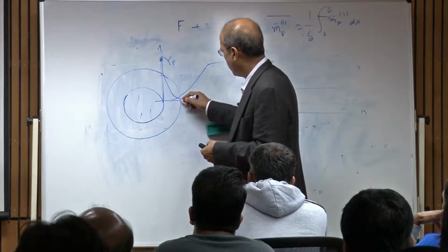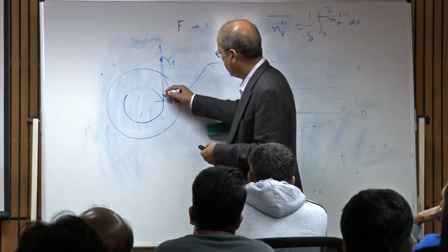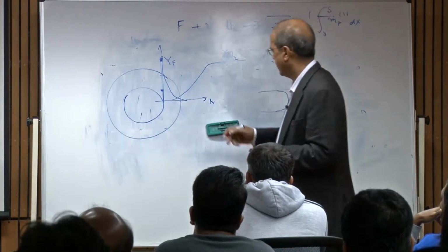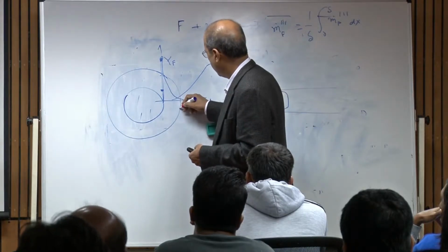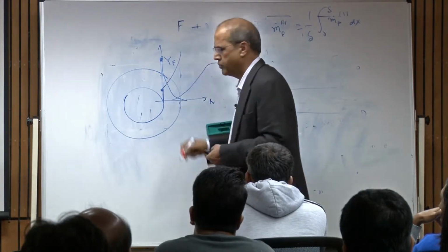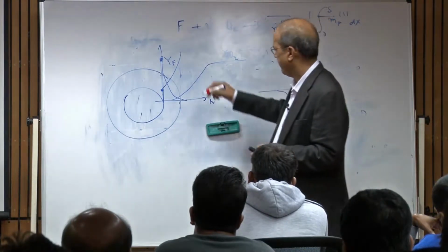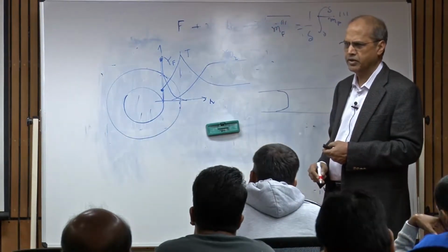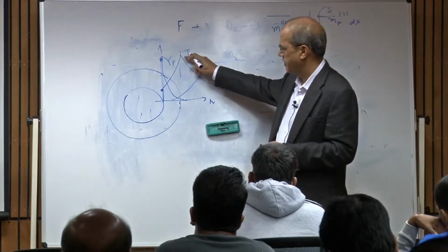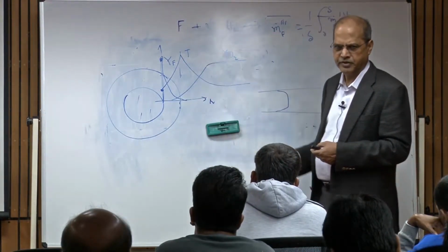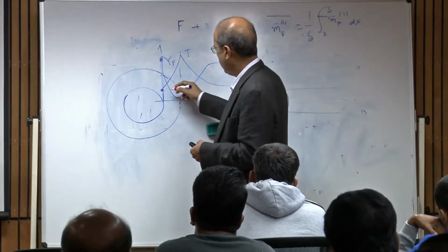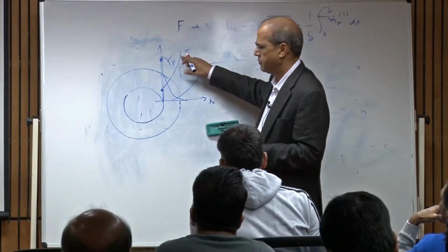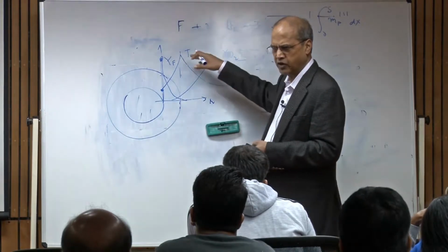The droplet temperature is relatively low, but it's higher than the ambient. If you plot the temperature, we have the peak value at the flame, and then it will drop. This is the variation of the temperature. You can imagine that this temperature will be close to the adiabatic flame temperature. Similarly, you can plot other species like CO2 and H2O. They will have their peak value at the flame, and then will drop off on both sides.